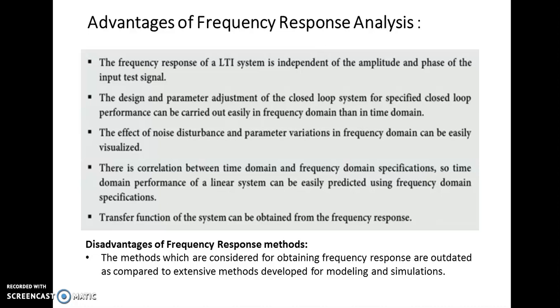The effect of noise, disturbance and parameter variations in the frequency domain can be easily visualized. There is a correlation between time domain and frequency domain specifications, so that the time domain specifications of a linear system can be easily predicted from the frequency domain specifications. The transfer function of a system can also be obtained from the frequency response methods.